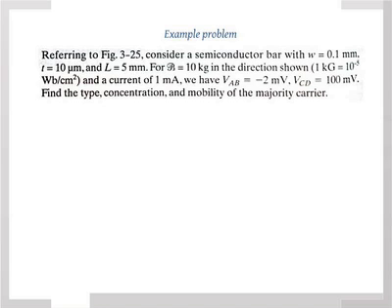So in the Hall effect, if the built-in voltage that you measure is negative compared to the applied voltage, then your majority carriers are electrons. And you can work it out in terms of the forces, just like we did for the holes. What's the next part? The concentration.